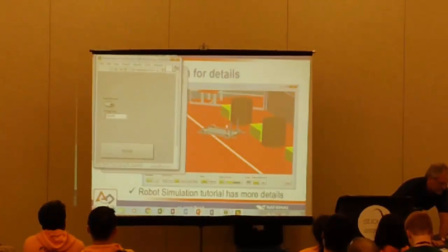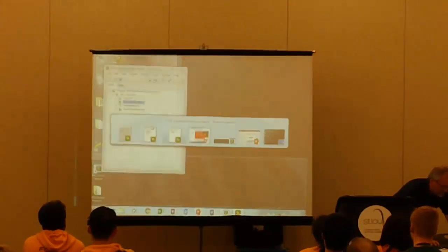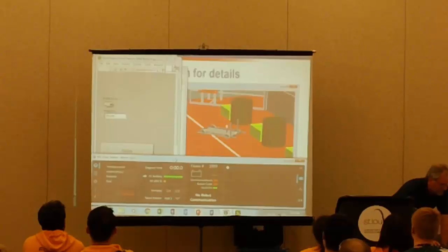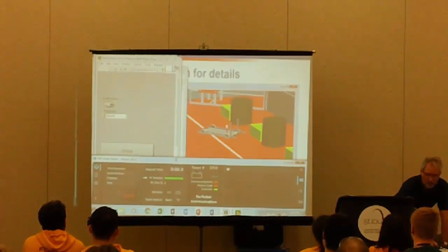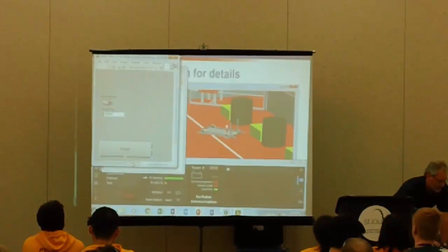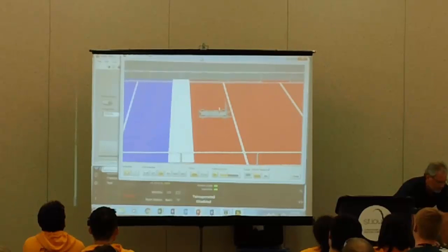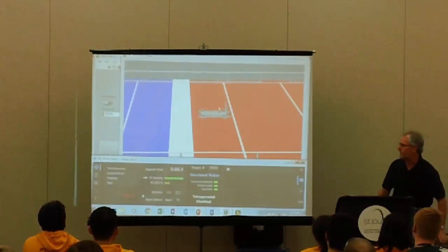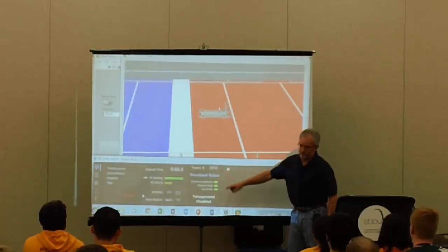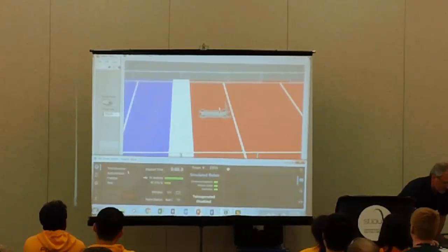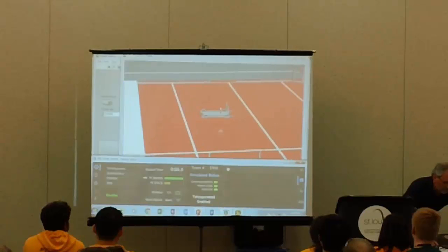So what I want to do is get all these pieces running, and it's a little bit tight on screen space here, but I think we can do it. So here's my driver station that you probably, if you run a robot, you're used to. Notice my joystick is connected. If I now run this, I'm set up on my computer. I can change that down in here. But I'm on my computer, so when I run it, the viewer opens up. And again, we're a little tight on space. But down here you can see that now it tells me I have a simulated robot, right? And so I can actually run this. I'm in teleop, and I can enable this robot, and then I can drive it in this simulator.